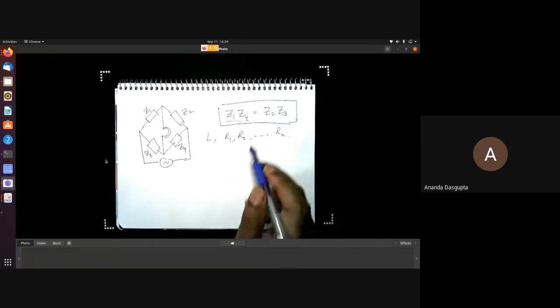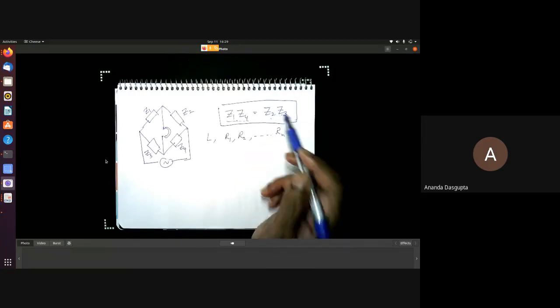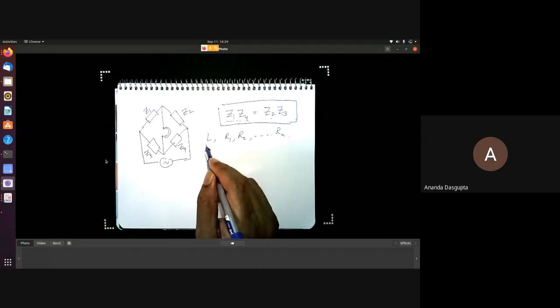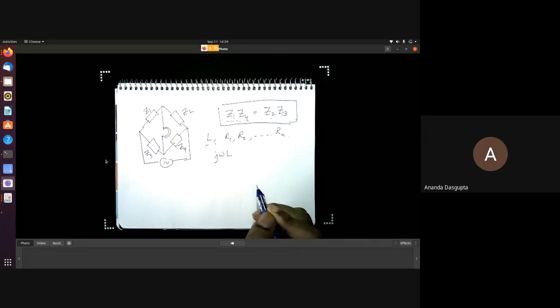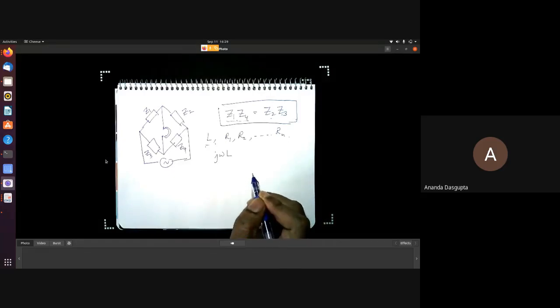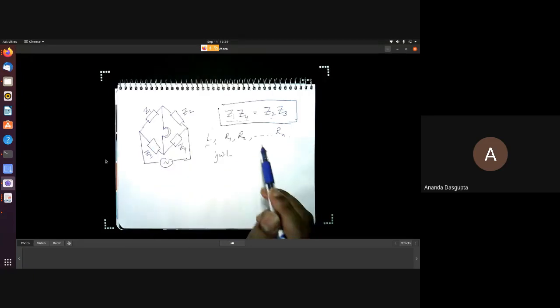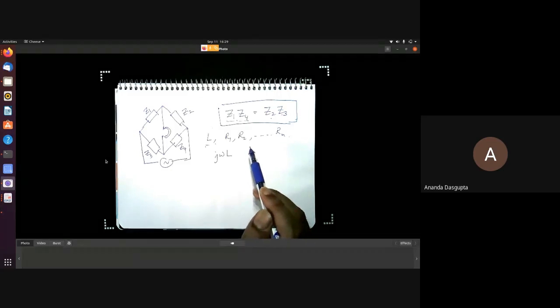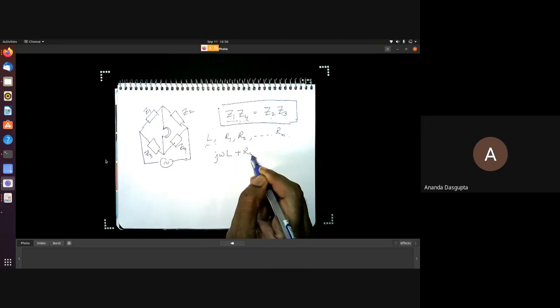Okay. So now that you have Z1 Z4 matching Z2 Z3, the moment you bring in a single inductance, that will bring in a j omega L impedance in whichever branch you put it. So right now 3 of the branches will have real impedances because you're only allowed to use resistances there, and one branch, 1, 2, 3 or 4, wherever, will have a complex impedance, a purely imaginary one if you just put in the inductance, but you could also put in, say, a resistance with it.